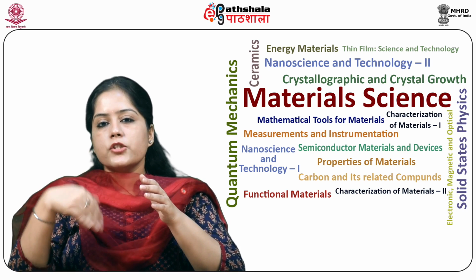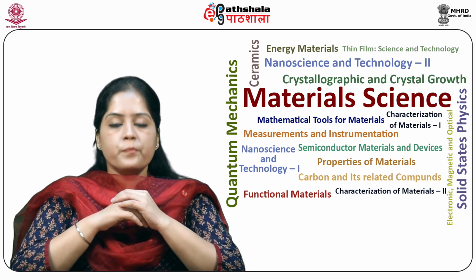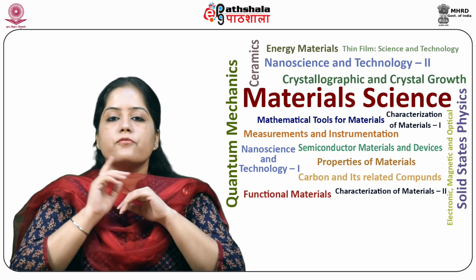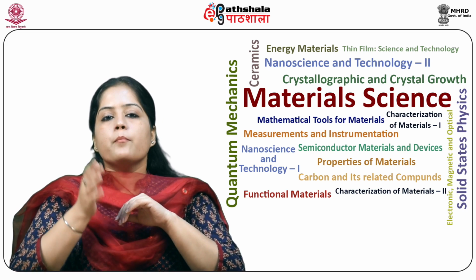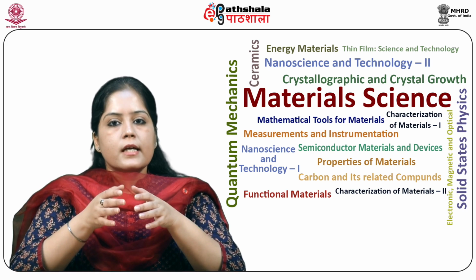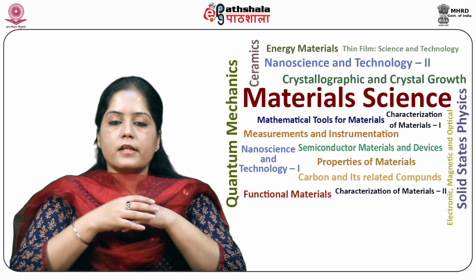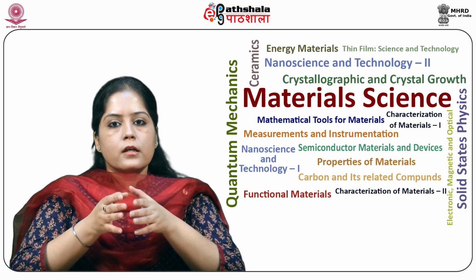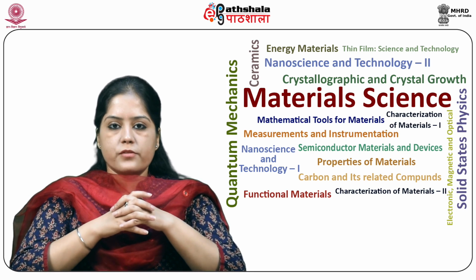It was only much later, after the problem of surface states was resolved by growing an oxide insulator on silicon, that the first MOSFET was demonstrated, in 1960 by Kahng and Atalla. Although the BJT reigned supreme in the early days of semiconductor integrated electronics, it has been gradually supplanted in most applications by the silicon MOSFET.